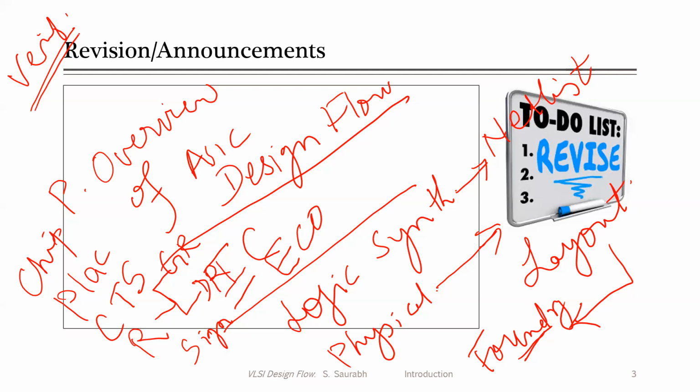To do that, we do wafer-level testing. We apply test patterns and see the output. To allow all of this to happen and to make the test efficient, we do something known as design for test. We make some changes in our design, and DFT, or design for test, is a group of steps that needs to be carried out during designing that helps in testing. So these things were discussed in yesterday's class.